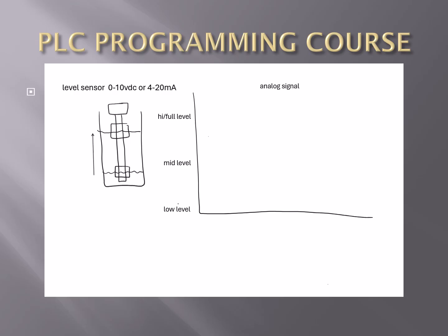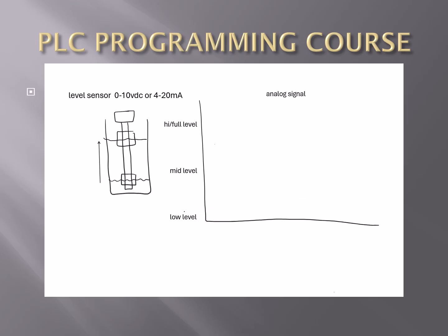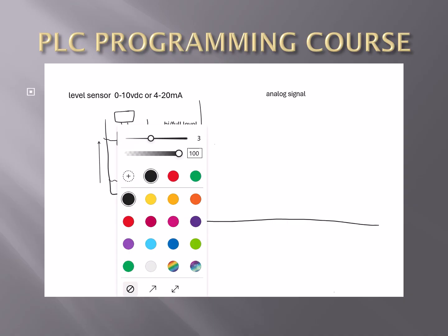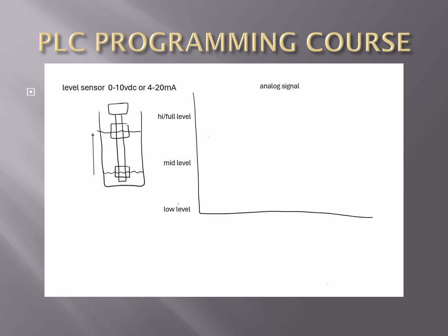As the float switch goes up in direction, you would start to see a rise in the analog output, and it would become maxed out when the tank is at whatever level. The issue here is you have to have your float switch scaled in length to equal your tank level. Pretty straightforward as far as that goes.